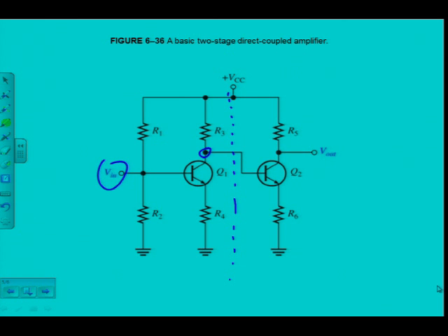And here then normally via a capacitor it would have been connected to a load resistor. But now I'm leaving out the capacitor. That's why they call it now a direct coupled amplifier. So now the capacitor is left out. So you can see already in the second stage there's no voltage divider. Why? I don't need the voltage divider because VC1, because there's nothing in between, is also equal to VB2.